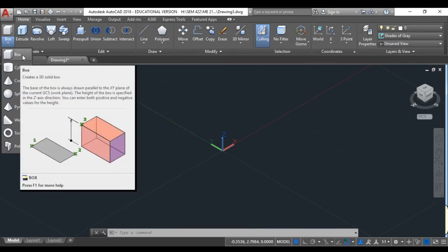Or maybe the program will ask me exactly what you can see in that picture. Look at the picture, guys. Can you see the picture, Bassam? In the picture, it seems that AutoCAD is asking you to locate the point 1, and then you move and locate the point 2. Look carefully, guys. Where is 1 and 2? They are in the same XY plane, right? So when you locate the point 1, you have to put it in terms of X, Y, Z.